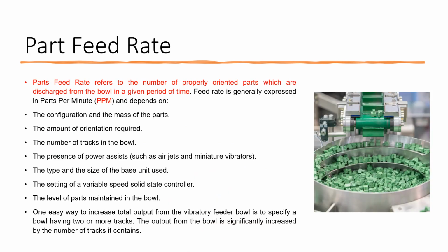Then the part feed rate. The part feed rate refers to the number of properly oriented parts which are discharged from the bowl in a given period of time, and generally the rate is mentioned as parts per minute. There will be many parts in the bowl feeder, and the part feed rate is very important: how many properly oriented parts it is giving per minute.